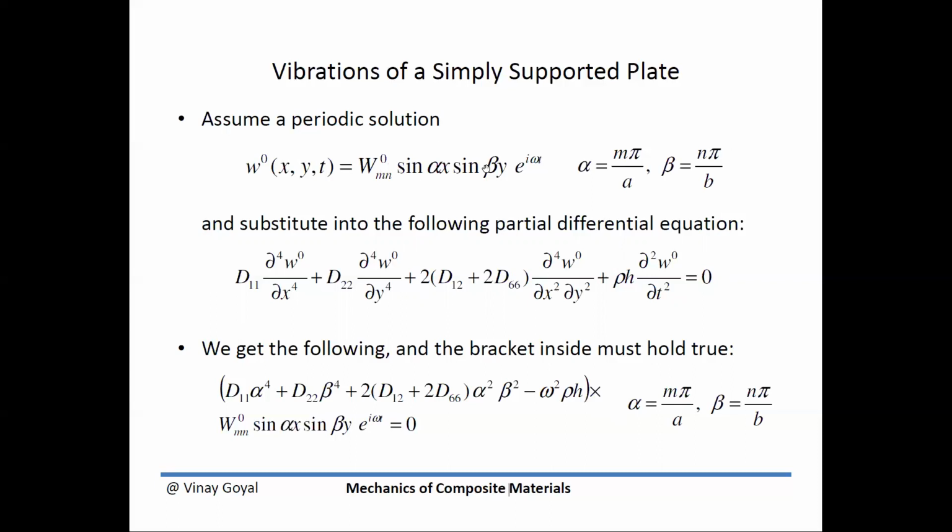As we stated earlier in the previous lecture, we demonstrated how by selecting these sine functions, we can automatically satisfy the boundary conditions for a simply supported plate, which means that around the edge of the plate, you should not have any deflections. And we can see here that if I set x equals a, the a cancels out, you get m pi, and sine of a multiple of pi, where m are integers, will be zero, and this goes to zero.